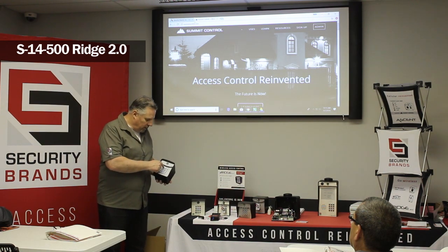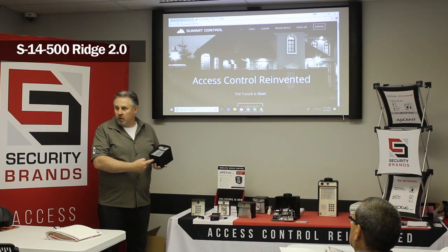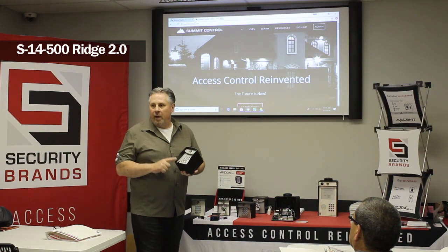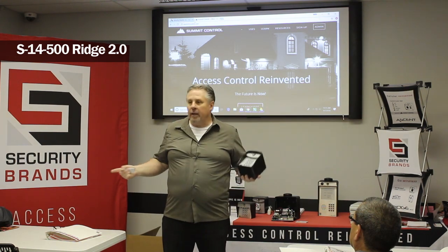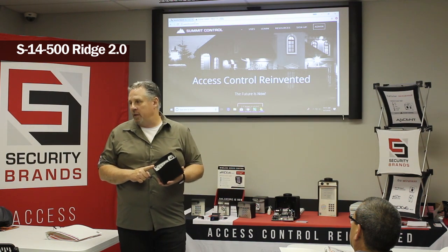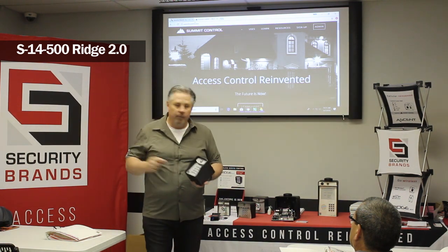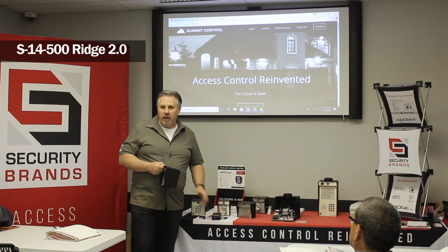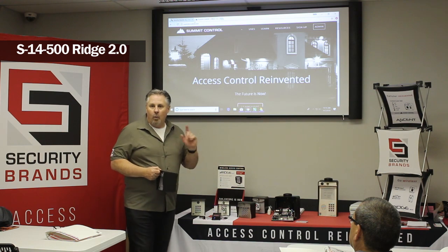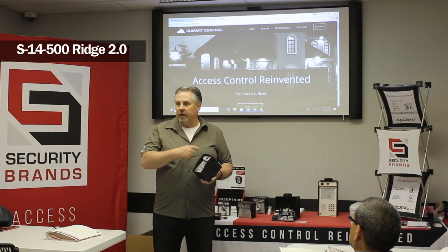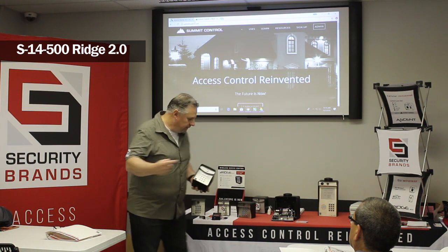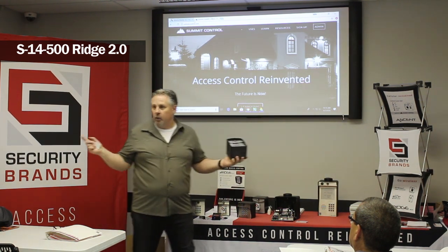So now let's enter that. You get a low tone coming from this and no tone coming from that. This will also handle, think of it like a 2 relay output keypad. But instead of relays, it has a frequency output, frequency A and frequency B. You would pair this for your gate operator by pressing the pair light on this. Once that light is blinking, you come to this device, you enter 1251 9 star 1. Then it finds this device and they pair together and you're done.